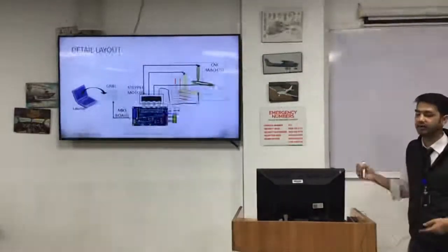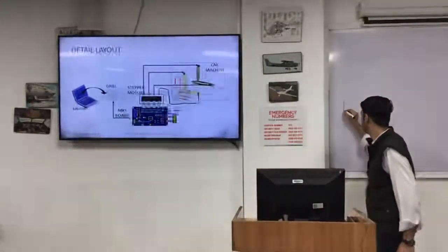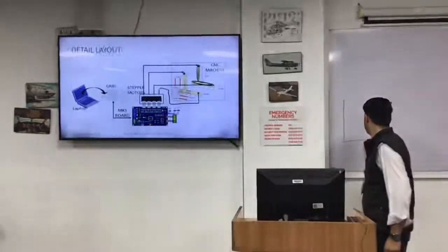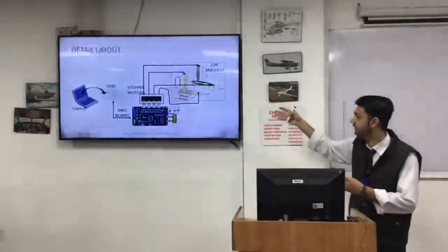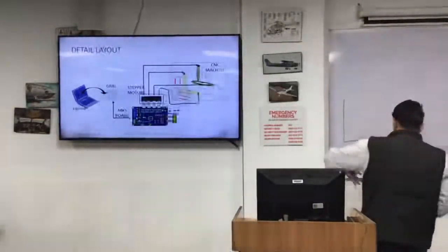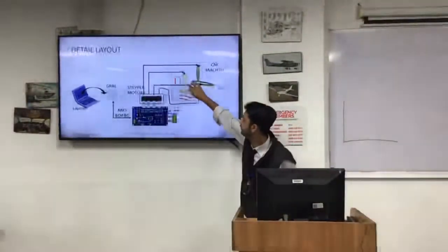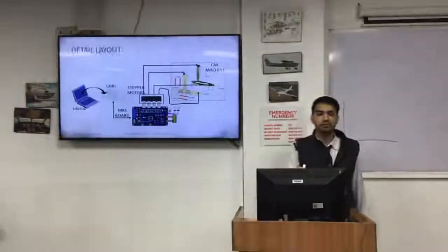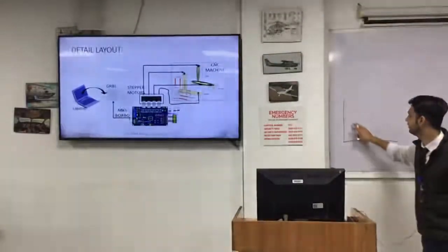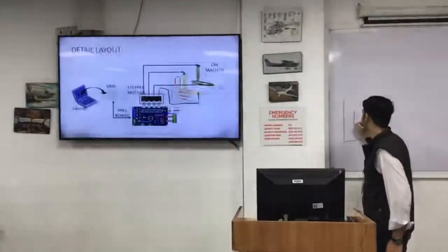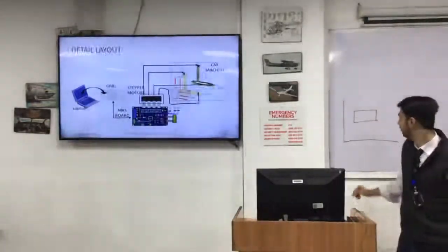We'll see a graph of how the machine can cut the form into an airfoil shape. Here is the y-axis, here is the x-axis. Let us consider that the machine is laying in this direction, like inwards of the wall. The wire that will be connected from this to this is called nichrome wire or nickel chromium wire. We can say that the wire is connected at this point. Here is the form that we are going to cut. It is usually a XPS styrofoam.